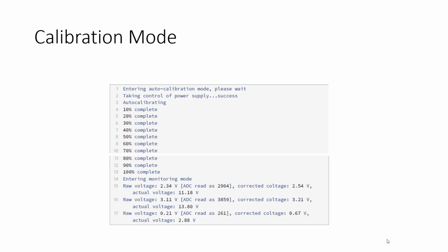Well, no, because remember, you're dealing with the UART and the communication. The rate at which you go through this is like 1 voltage every, I don't know, 100 milliseconds or something. It's kind of slow. And you have to give the power supply time to stabilize after you change the voltage, because if you don't, it'll give you a voltage that isn't correct. Do we have a number for that? I don't remember. It's kind of arbitrary. Just wait a little while to give it time to stabilize. I hope the lab sheet says that.